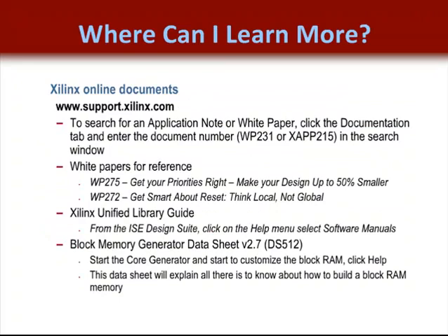Well, there are lots of places to learn more about FPGAs, and they all start at support.xilinx.com. I want to point out that I referenced several white papers that you might want to check out. They all provide more information on optimizing your design and optimizing the HDL coding for the 4-input LUT. Finally, we spoke about the Xilinx Unified Libraries Guide. It provides insight into the primitives available to designers for each device family. This will explain how to customize the initialization of the block RAM resources and what sizes of block RAM primitives are already available. I recommend you check it out.